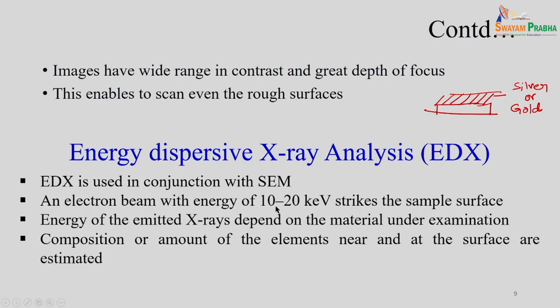So, when the electron beam with the energy in the range of 10 to 20 kilo electron volt strikes the sample surface, then as I told, the energy of the emitted X-ray depends on the property of the material, or you can say the composition of the material, and this composition or amount of the material is estimated depending on the energy of the emitted X-ray.